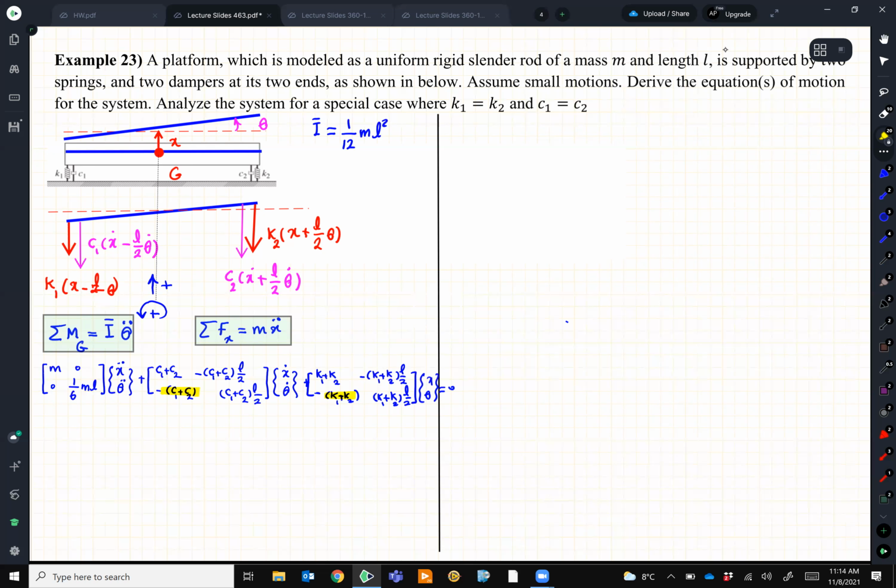But remember the Euler law: you always have to take the moment either about the center of gravity or about the point where the whole thing is fixed and joined. The reason we do the moment about the center of gravity, as I explained in early lectures, is that we want to get rid of the ma, since there is an acceleration at the center.